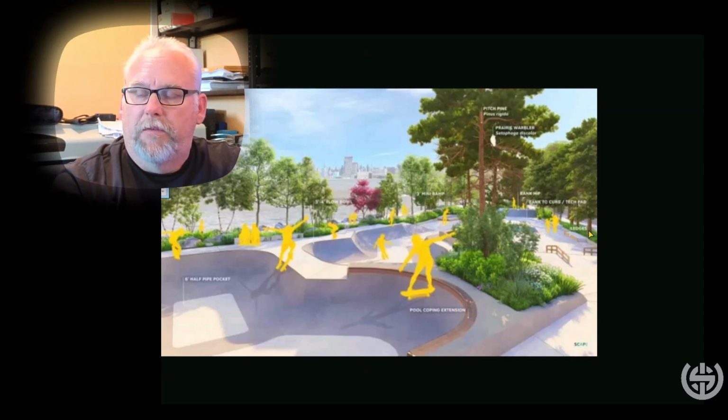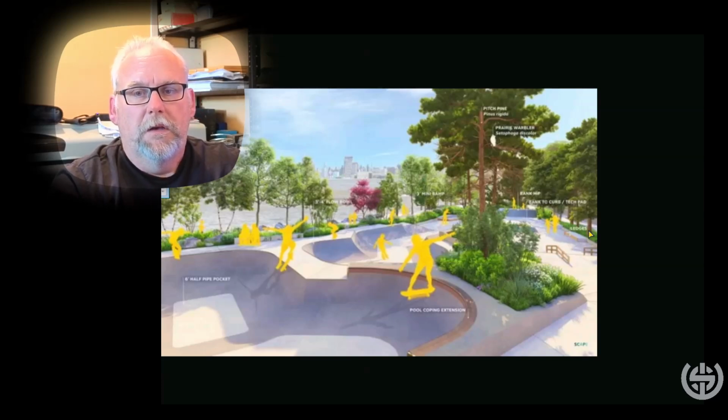Being next to the river there, I would actually not do powder coated. If there's a cold galvanized product, I would do galvanized fencing. If there's not a good galvanized product, I'd do stainless steel. And we'll take a look at what I've got around the park.